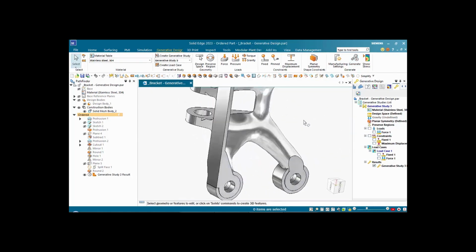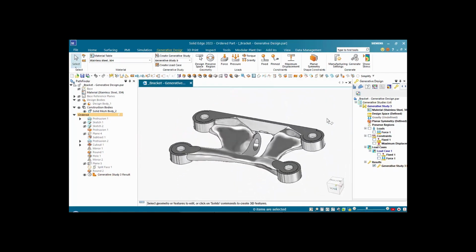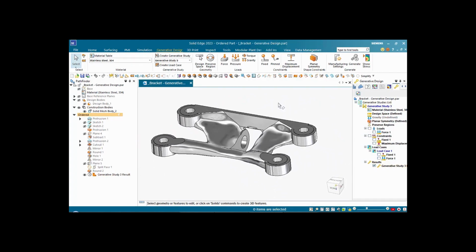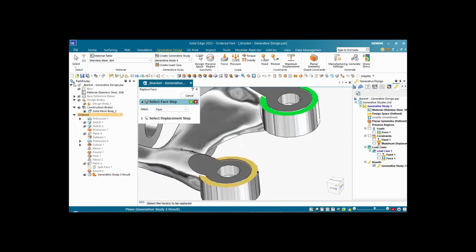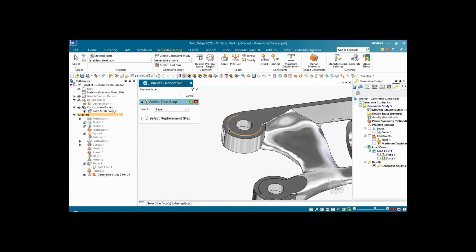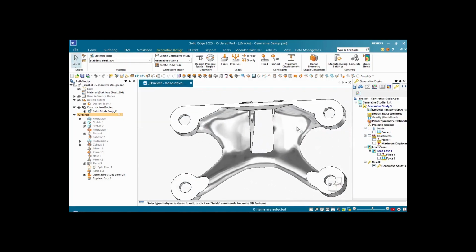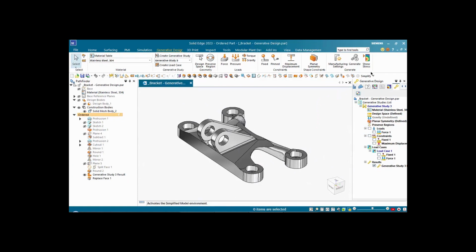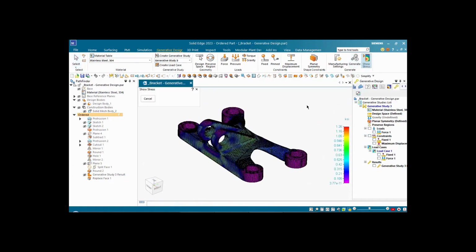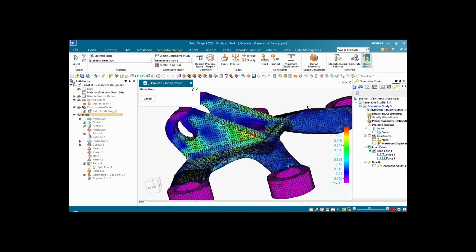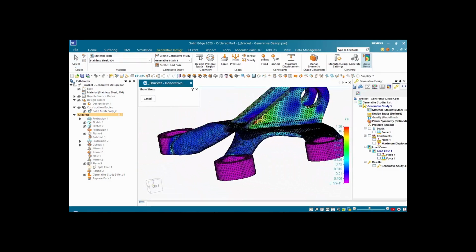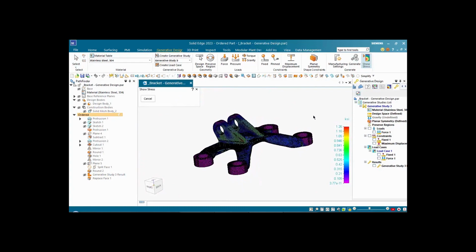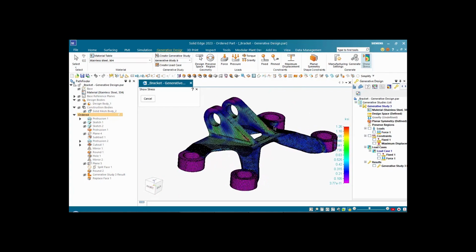So now you can see we have this front wall added. We have ability to actually clean up this model, as I mentioned earlier. Conveniently, Solid Edge provides tools for very efficient way of dealing with this. We can just clean up this face and avoid that little step up front. So conveniently, of course, we can take a look at stresses after we generated this final body. And you can see that our model actually reaches certain stress, and you can see the stress concentrators.